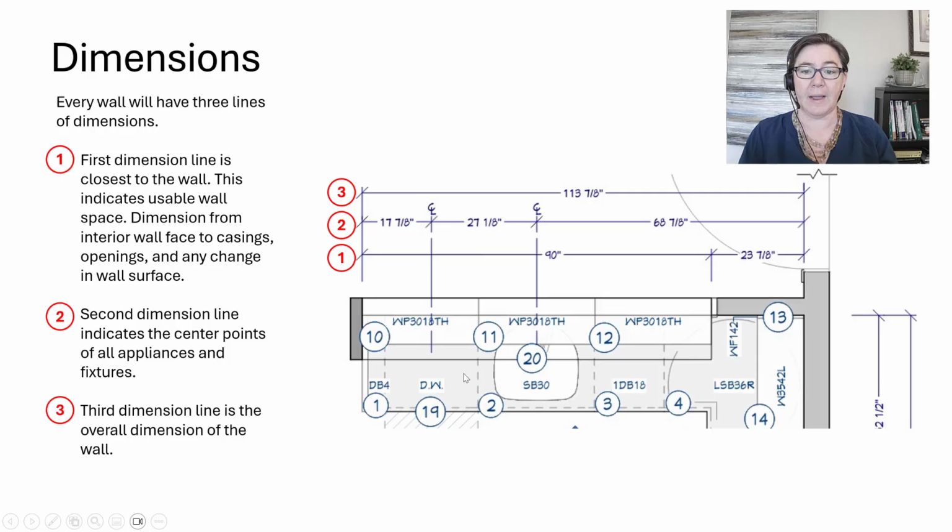Now, I do recommend, and it's shown here in this drawing, that once you place this center line dimension, which typically, whether you're using Chief or AutoCAD, you kind of snap to the back of whatever piece this is, you go ahead and grab that line and you pull it down to the center of your elements. This makes it way easier to read and to tell exactly what is being dimensioned. And you can see that again here with this one. Notice that your center line measurement is using a center line type, and it's got the center line symbol.